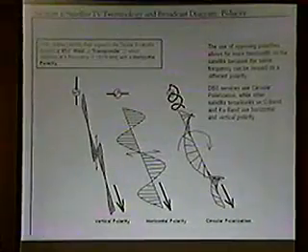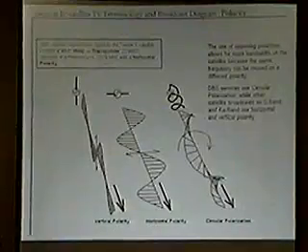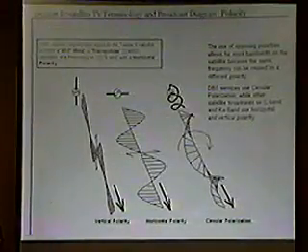It's completely non-standard. They're the only basic services that use it, and so it's really difficult to deal with. But they do it because terrestrial interference happens all the time because the surface waves from the Earth have a vertical polarity, and so they mess up a lot of the satellite communications. Not on a regular basis, but when it does happen, it's bad.